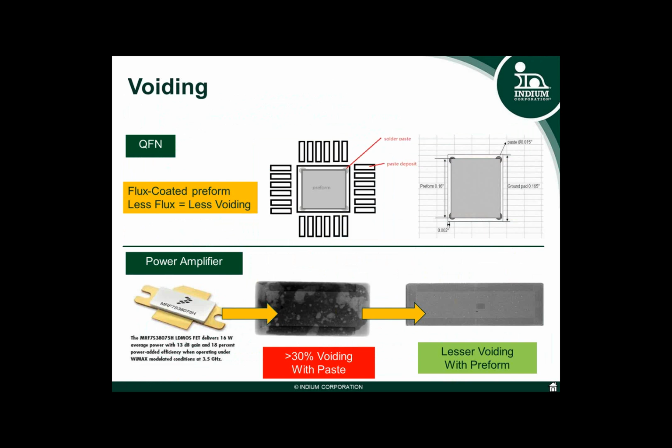So there's a standoff that needs to be filled with solder volume. And again, the stencil printing techniques and the step stencils may not accommodate those design features. So the addition of the solder preform, again, with or without a flux, depending on the process, can be increasing the solder volume as desired.